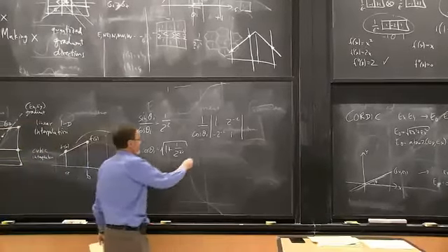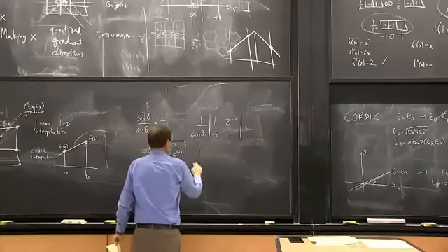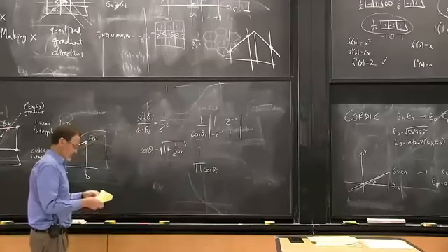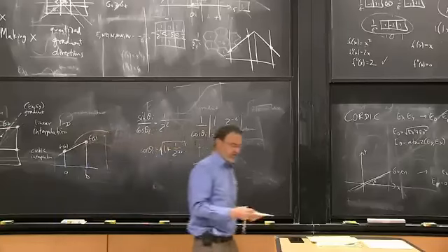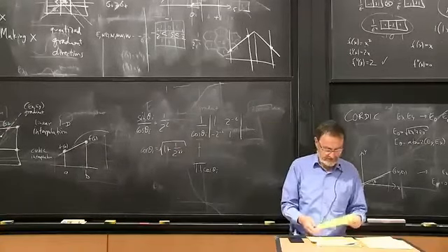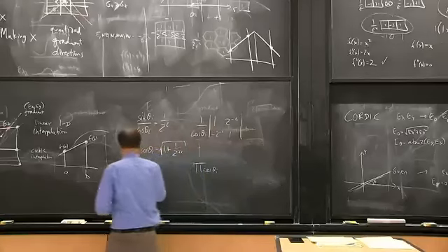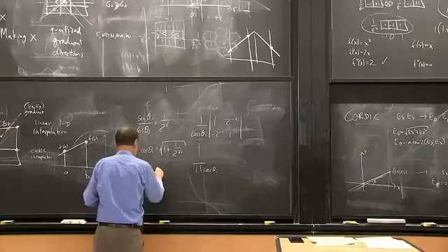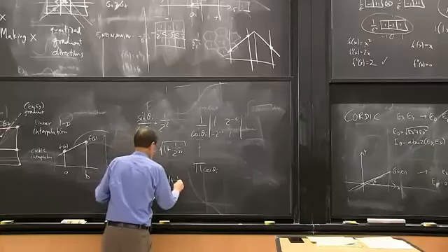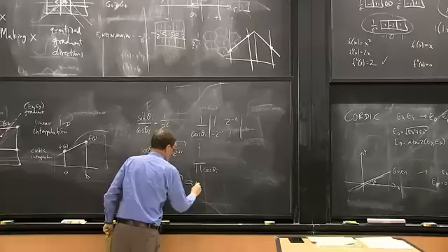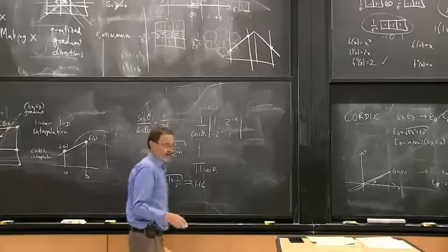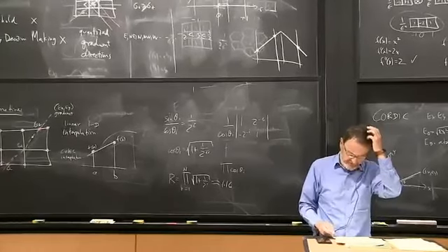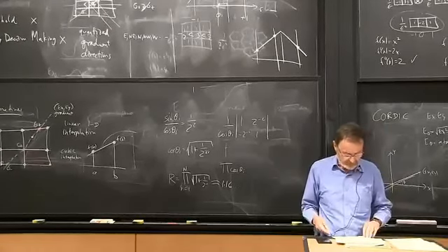And then when you're done, you end up with a product of all of these cosine theta i's. And so what do you do with that? Well, maybe you don't care because it's just a constant multiplier. But suppose you do care, then you can pre-compute it. And actually, it's 1.16 very quickly. It converges very fast. So you can just use 1.16.